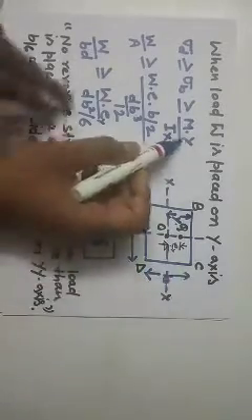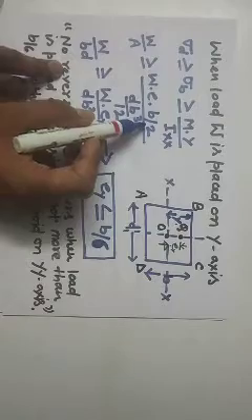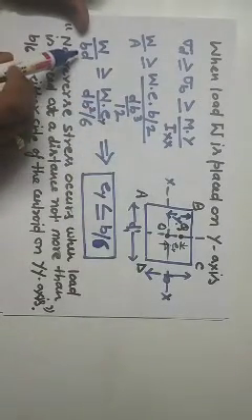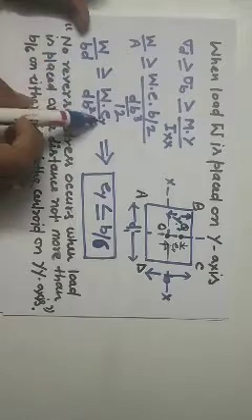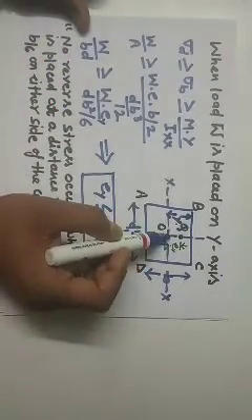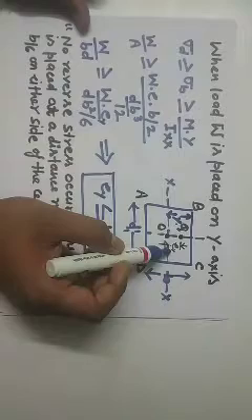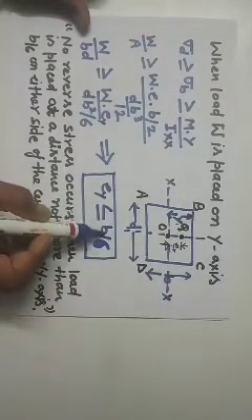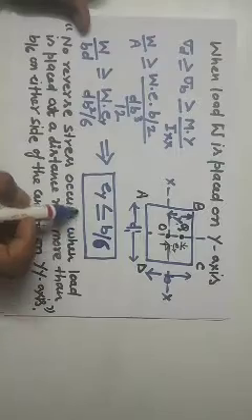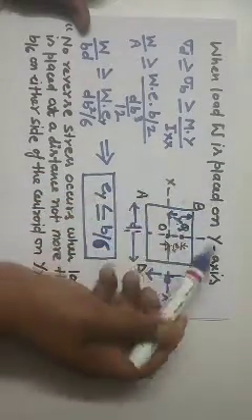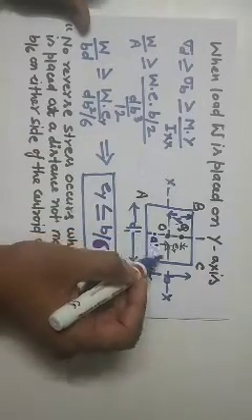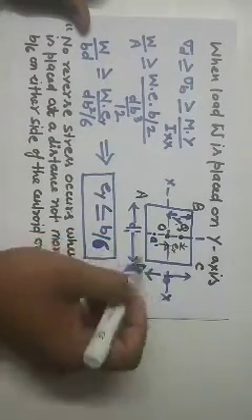Then put this value here: y is equal to b by 2, Ixx will be d b cube by 12, and area is b d. Since the eccentricity is measured on the y-axis, I call it ey. So ey will be less than or equal to b by 6. And if W is placed on the negative y-axis, here at point Q dash, the answer will be the same for this condition.